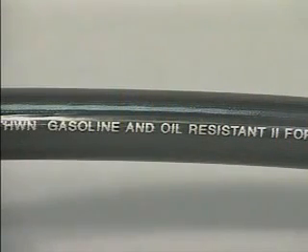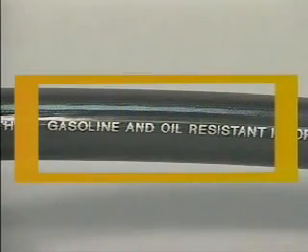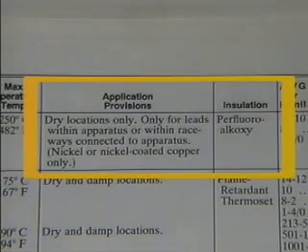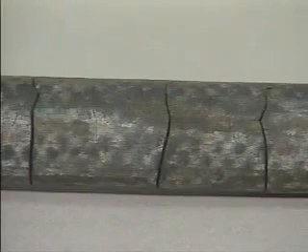Different types of insulating materials provide different types of environmental protection, so conductors are also classified by insulation type. For example, some types of insulation are designed for dry environments and may tend to rot when they're exposed to high amounts of moisture. On the other hand, the types of insulation that are constructed to hold up under high humidity may tend to dry up, crack, and peel in an extremely dry environment.